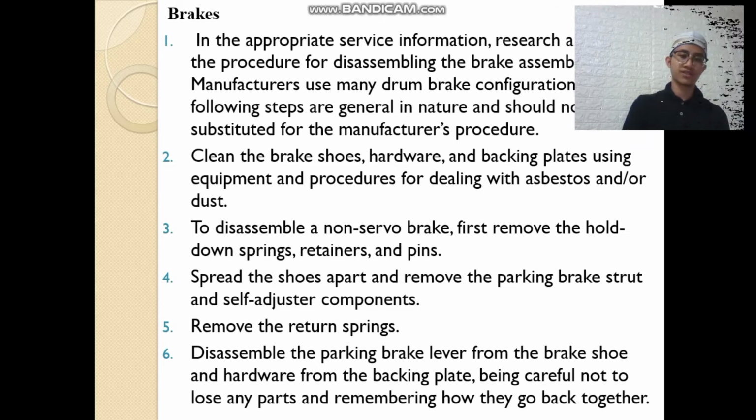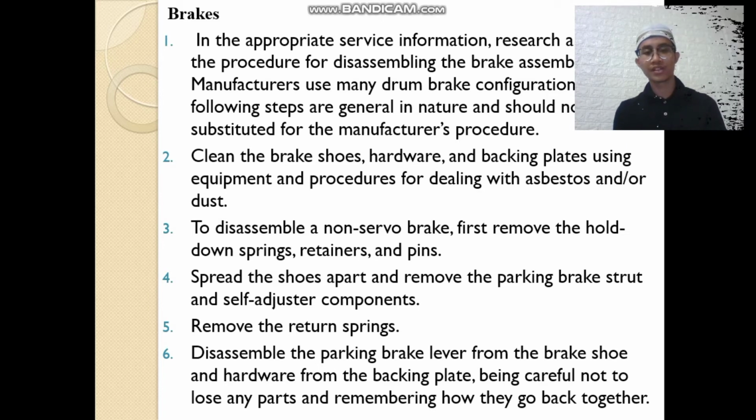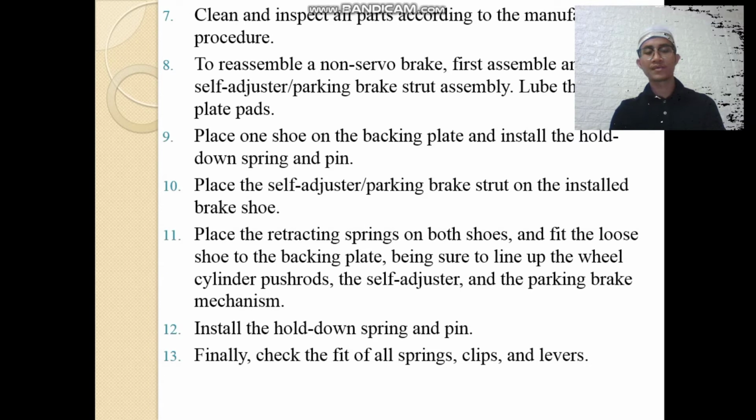The sixth step is to disassemble the parking brake lever from the brake shoe and hardware from the backing plate, being careful not to lose any parts and remembering how they go back together. The seventh step is to clean and inspect all parts according to the manufacturer's procedure.